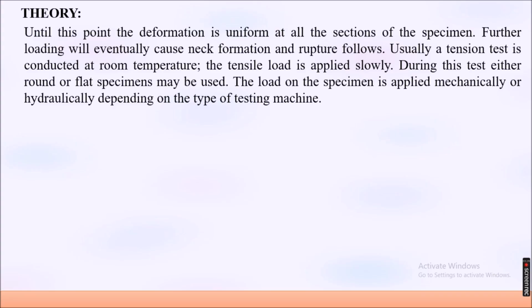Usually a tension test is conducted at room temperature. The tensile load is applied slowly. During this test, either round or flat specimens may be used. The load on the specimen is applied mechanically or hydraulically, depending on the type of testing machine.